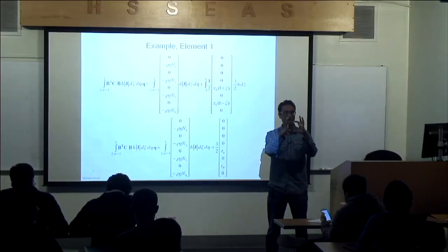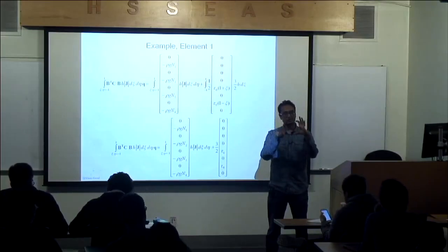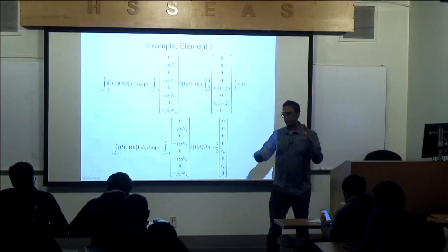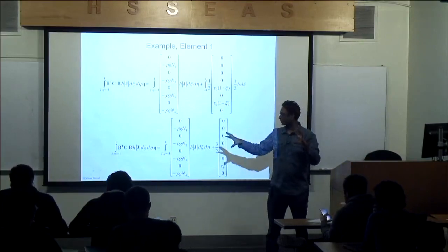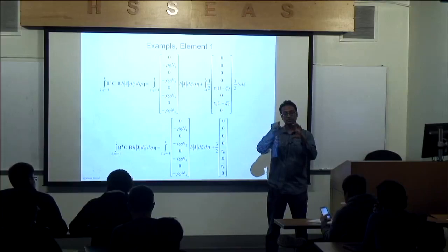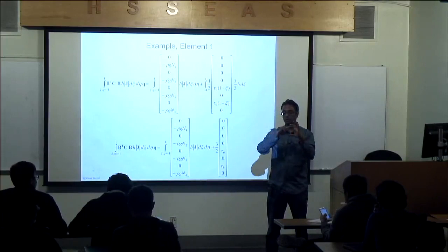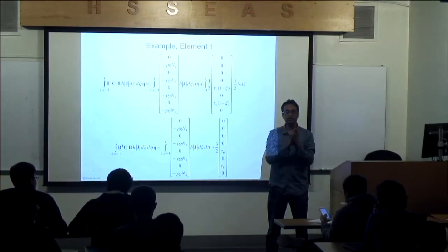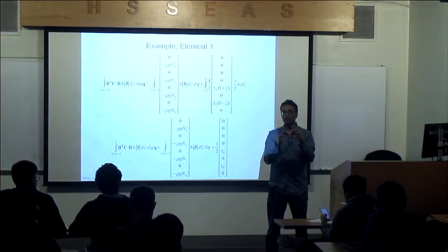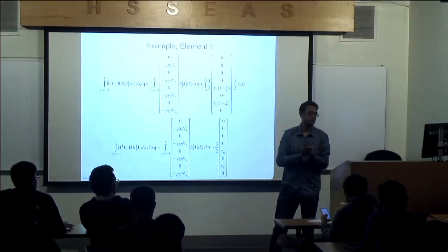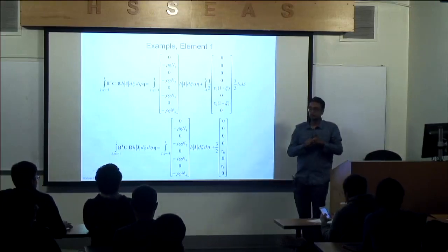So at the element level, you have a square, or whatever it is. If I do this integral, I think the code is going to put rho g of that element divided by the node. So it would be rho g divided by 4. It also needs to consider the area. So the area of the square is about 9 times the thickness 1. So you can calculate the weight, and it will be putting a fourth of the weight at each node. I think that's what it's going to do. Check it out. Tell me what you find. I'll be interested.